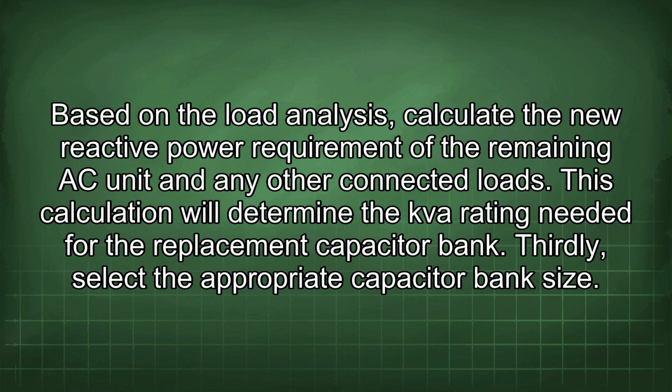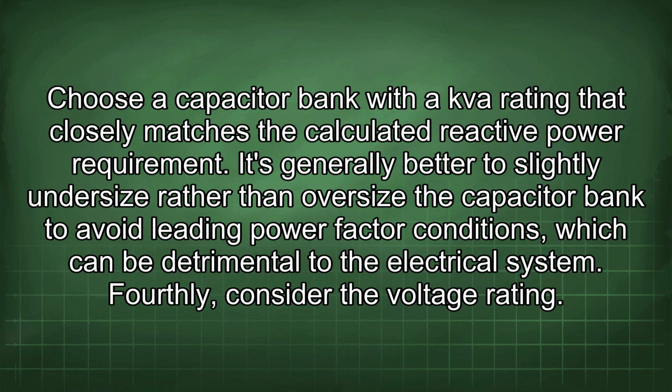Thirdly, select the appropriate capacitor bank size. Choose a capacitor bank with a kVA rating that closely matches the calculated reactive power requirement. It's generally better to slightly undersize rather than oversize the capacitor bank to avoid leading power factor conditions, which can be detrimental to the electrical system.